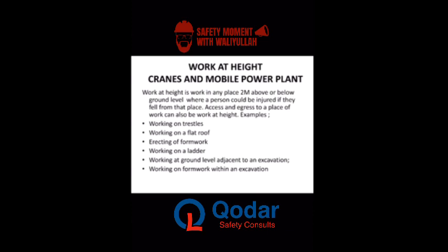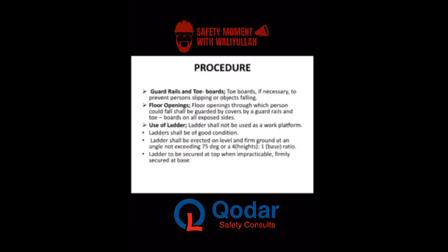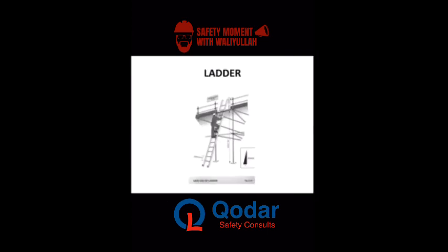If you're working with a ladder, note that a ladder is not a working platform. A ladder is not a working platform. Rather, it is important that we look for ways to set up a proper scaffold where necessary. We also need to have guardrails and toe boards. We also need to guard against all forms of floor openings and cover them with boards on both sides, so that someone walking can walk comfortably on that platform.